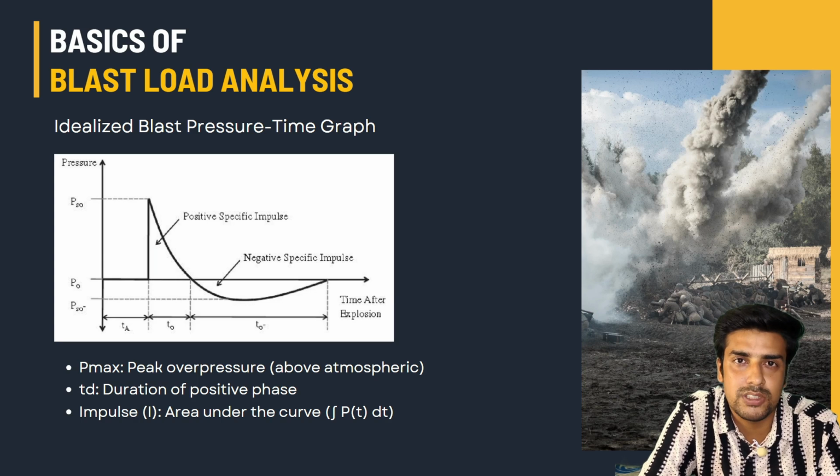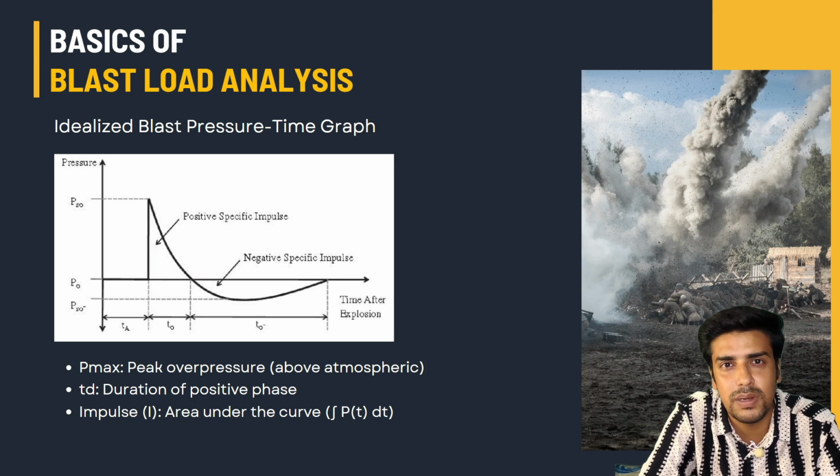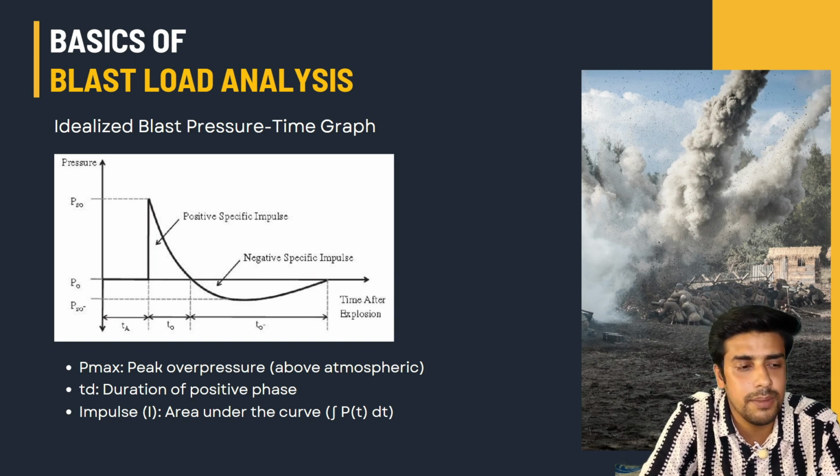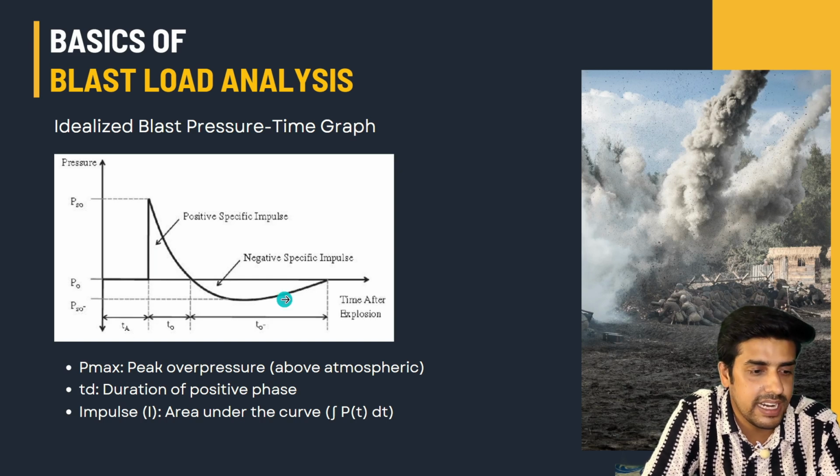It is the same thing. Whenever the impact happens, the load starts at the peak, and it will decrease, not slowly, but very rapidly, in a moment. The blast duration is very small, like 0.003 second or 0.05 second. So the load is at its peak at the start point, then it drops in a very short instant of time, and after that it gives the suction. It gives a negative pressure there.